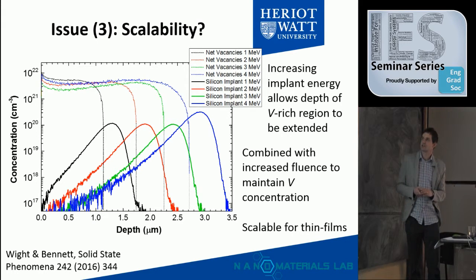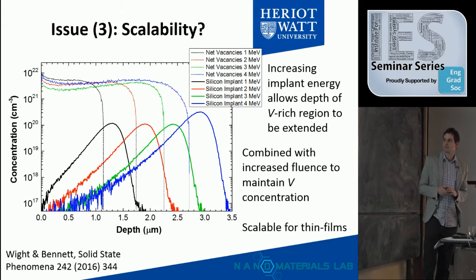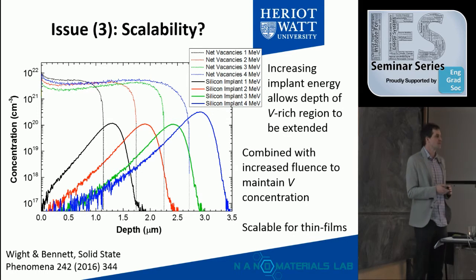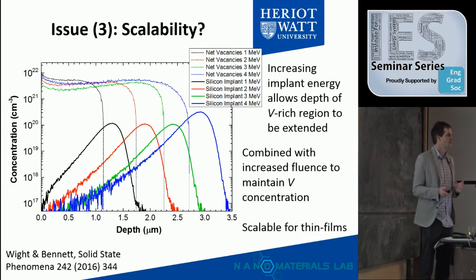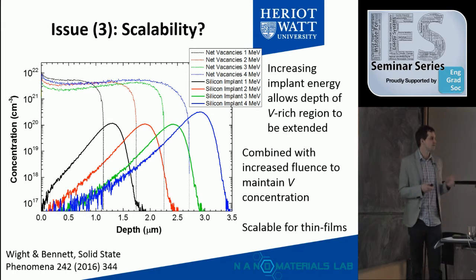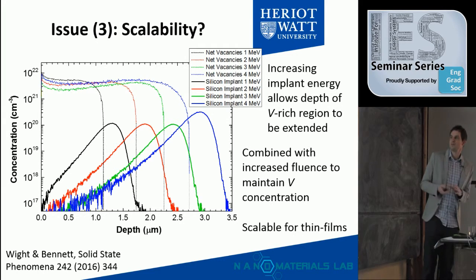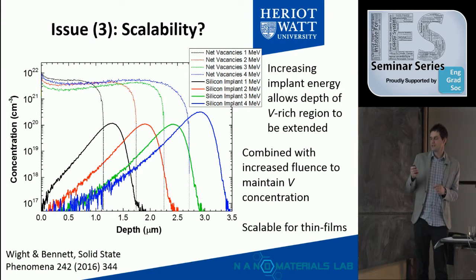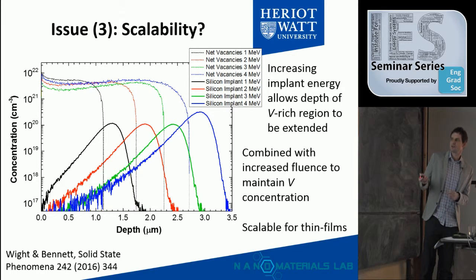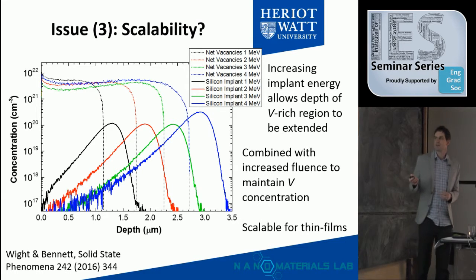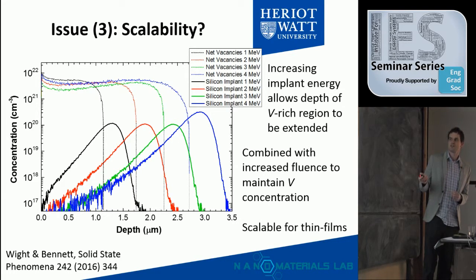So I said I'd come back to scalability. Really, the processes we use are quite easily scalable. You can up your implant energy for your ion implantation to modify the extent to which the vacancies impinge into the substrate. You can see this hopefully here. These are our ions at various different energies, and you can see the net vacancy profile from the simulation.